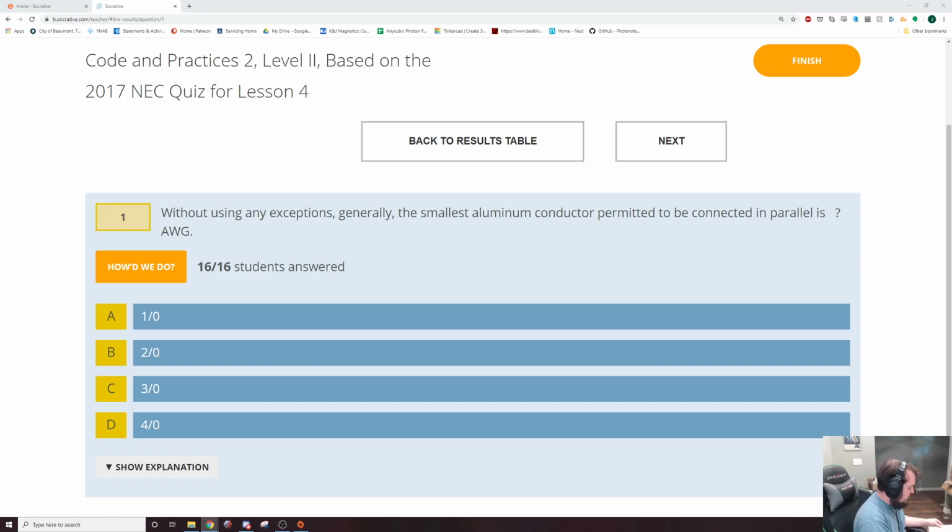For those of you not familiar with what this is talking about, installing conductors in parallel is whenever the math says you would require 1,000 kcmil wire, and you do not have the resources to pull a wire that size. 1,000 kcmil, not 1,000 circular mils, which would be smaller than these wires. 1,000 kcmil is bigger than a water hose.